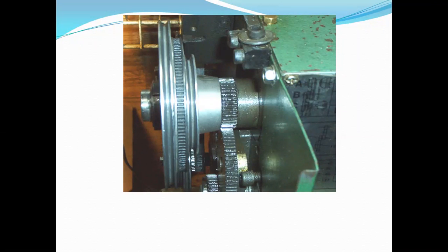So what we are doing here is applying lubricant at this mating zone. Because of this lubricant, there is a reduction in friction. Due to this reduction in friction, we are reducing the heat generation also. Due to less heat generation, we are increasing the metal life. Okay.